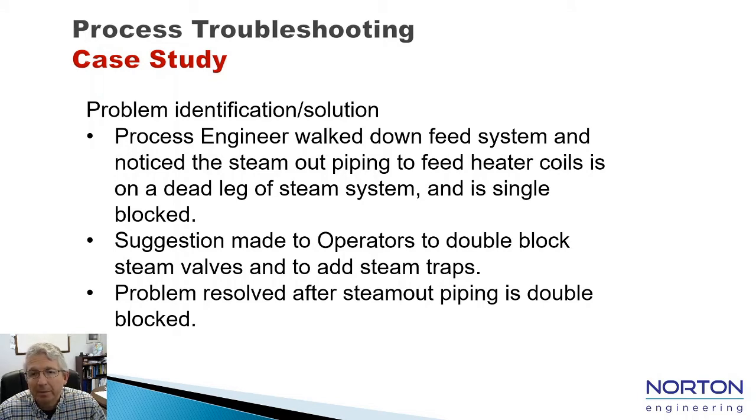Thinking that might be a potential cause of this issue, a suggestion was made to operators to double block that steam valve and to add some steam traps to make sure that we didn't have any condensate building up in that leg. Sure enough, the problem was resolved after that steam out piping was double blocked.